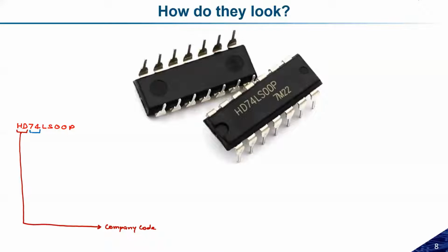in that case the temperature can range from an extreme negative to an extreme positive, because those ICs can be used for military applications in extreme weather conditions. So we need to develop two kinds of ICs: one for commercial and the second for military purposes. This 74, the code in the second, third and fourth digits, indicates the type of IC we have. If 74 is written, it means this is the commercial one, applicable for commercial use.